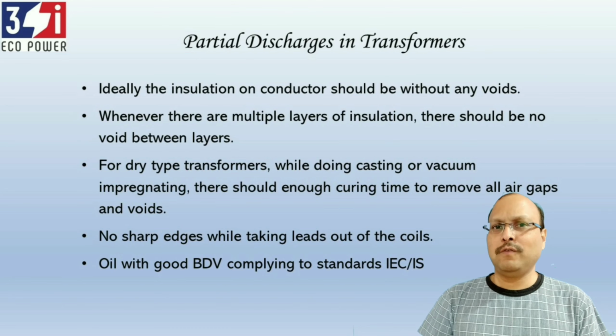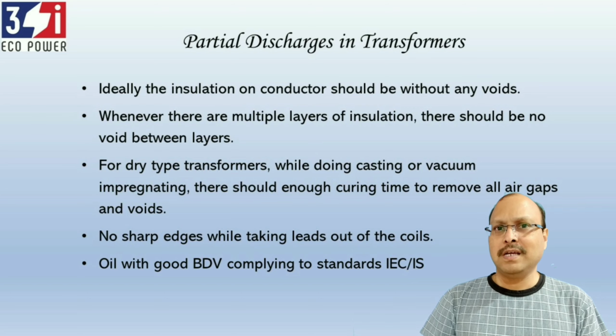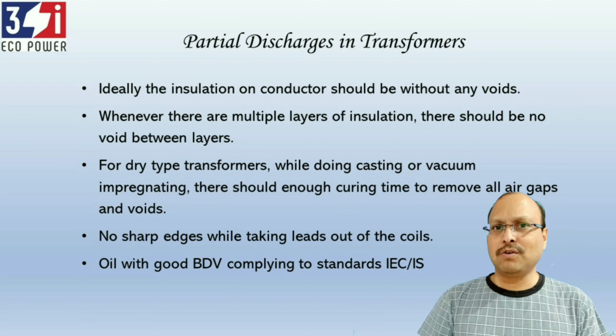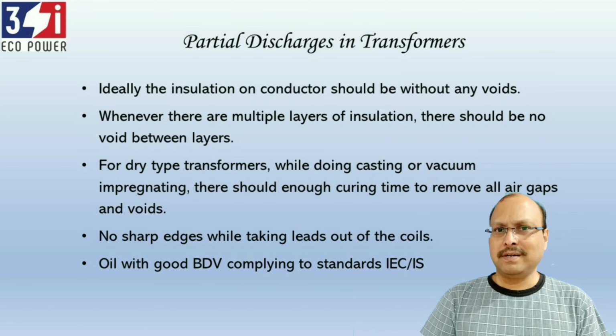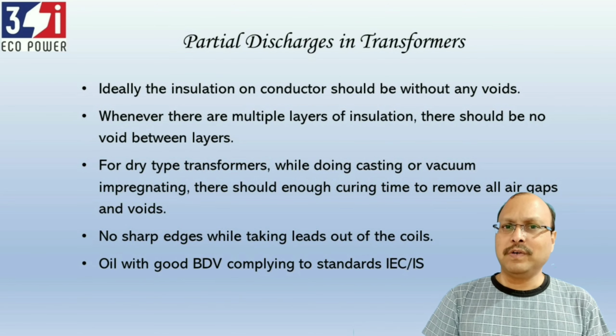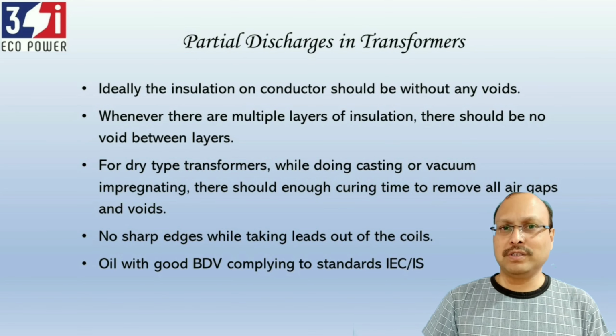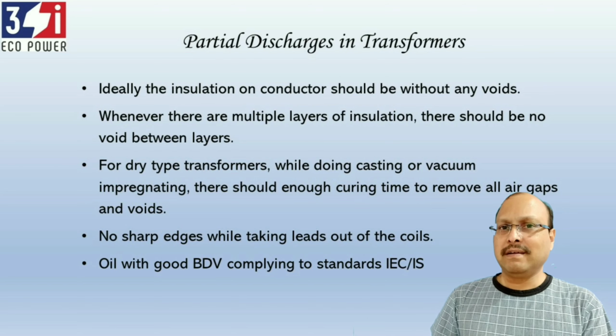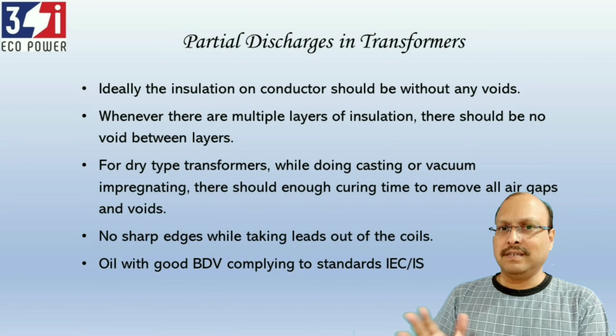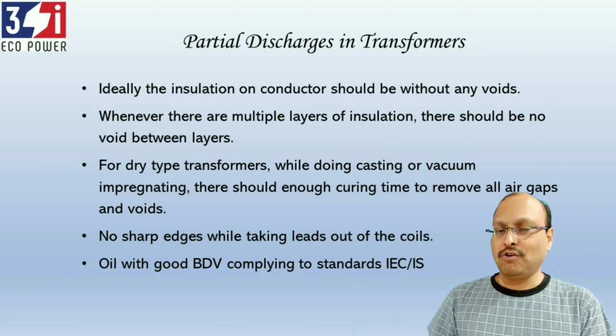How? If it is an oil-filled transformer, you do proper oven cycling, and after that you fill the oil preferably under vacuum, and give some settling time so that oil is absorbed in all places, with no voids or air bubbles. So this is one important criterion. Even when filling oil, ensure it's properly done. And for dry type transformers, if it is a vacuum impregnation or casting process, ensure again the settling time of the resin. You should give enough time so that the resin is absorbed in all places.